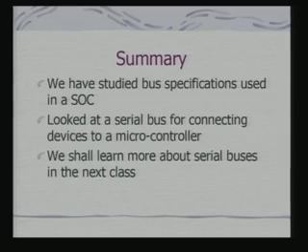So, here what we have done, we have studied today the bus specification used typically in an SOC, and looked at the basic serial bus for connecting devices to a microcontroller. We shall learn more about the serial buses in the next class, because you have got the SPI bus, and also the bus definitions for connecting peripheral devices. Other bus definitions, particularly for IO devices like USB and FireWire, we shall look at in the next class.